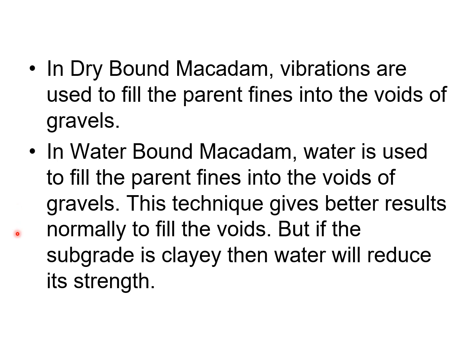But if the subgrade is clay, then water will reduce its strength. You know, when the moisture content of the clay increases, there will be a drastic decrease in the shearing strength of the clay because of the reduction in the cohesion, or you can say the shearing strength.